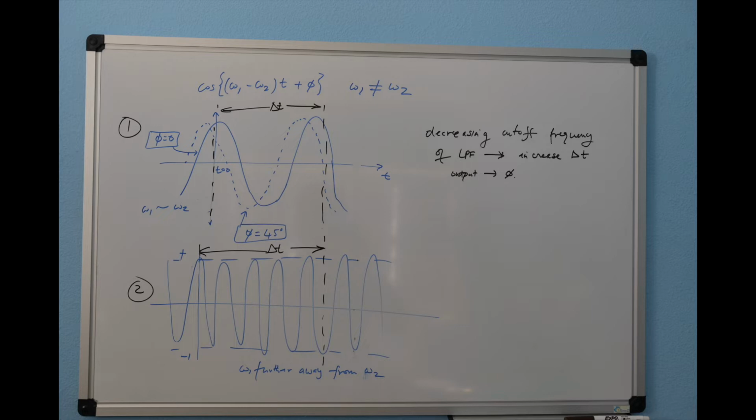So this particular aspect of the lock-in amplifier might be a little bit difficult to visualize at this point. That is when the two frequencies of interest are very, very close to each other but not completely equal, in which case you have this time varying component in the phase that shows up on the output of your lock-in. So we look at this in the simulations and perhaps also in the demo to better illustrate this effect.